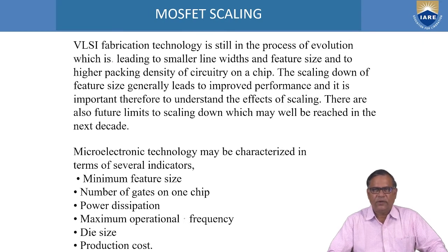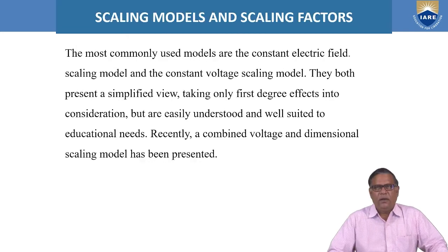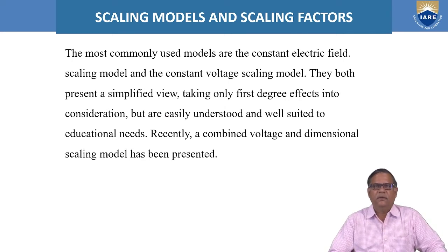Microelectronic technology is characterized by several indicators such as minimum feature size, number of gates on the chip, power dissipation, maximum operating frequency, die size, and production cost. To study the effects of scaling, the phenomenon of scaling can be best described by three models: the constant electric field model, the constant voltage model, and the combined model.